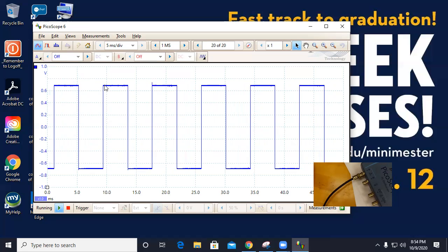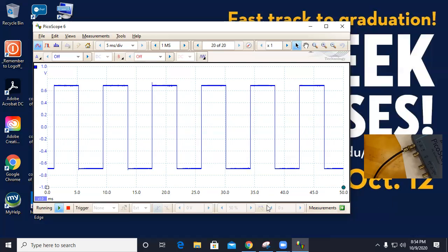So you can look at it and take a measurement. That's the voltage, it's between minus 0.8 to minus 0.6, like minus 0.7, I think, to plus 0.7. As you see, there is no DC offset, as explained last time. If you want to see it more clearly, you just go here to the scale. That's the scale of the frequency, 5 milliseconds per division. That's controlling this x-axis. Just move this one. That's the axis, it's in milliseconds, shown here. So I'll just go ahead and let's see what happens if you decrease it.